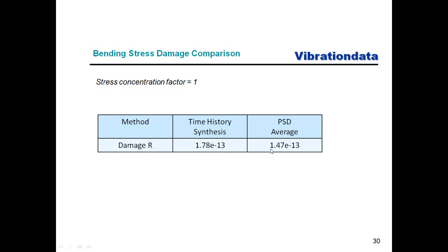And the fact that there is some 10 to 15% difference, whatever it turns out to be, we're not going to worry about that because, again, you have to remember, we're dealing with a fatigue exponent of 9.25. So any small differences get expanded very greatly by that fatigue exponent.